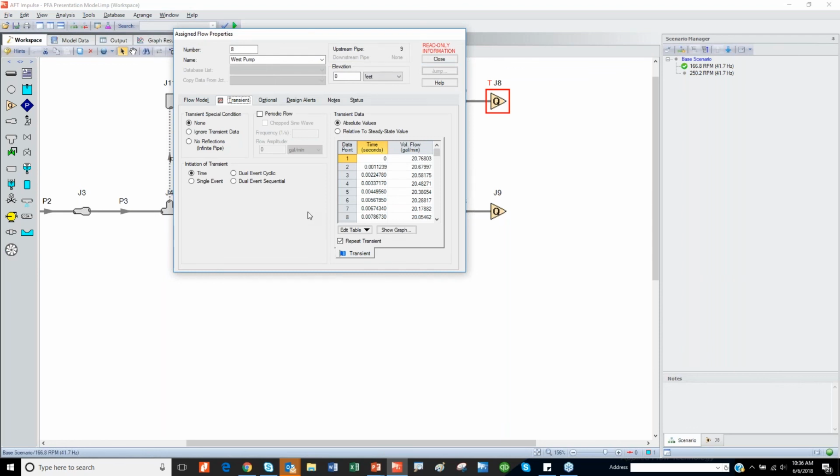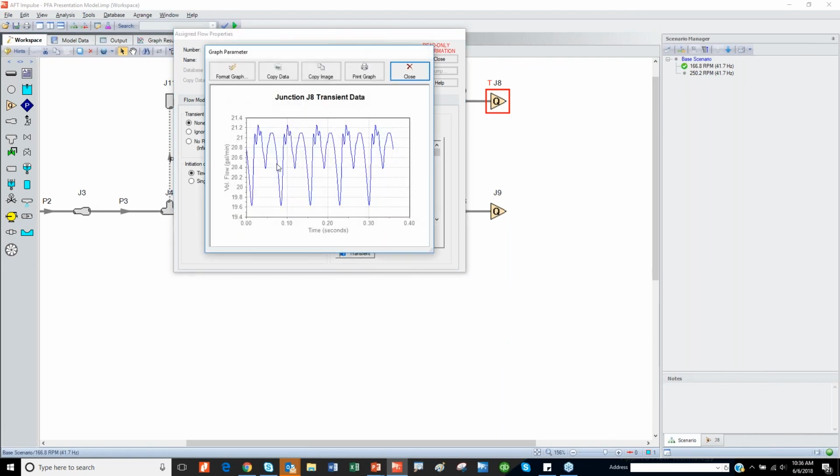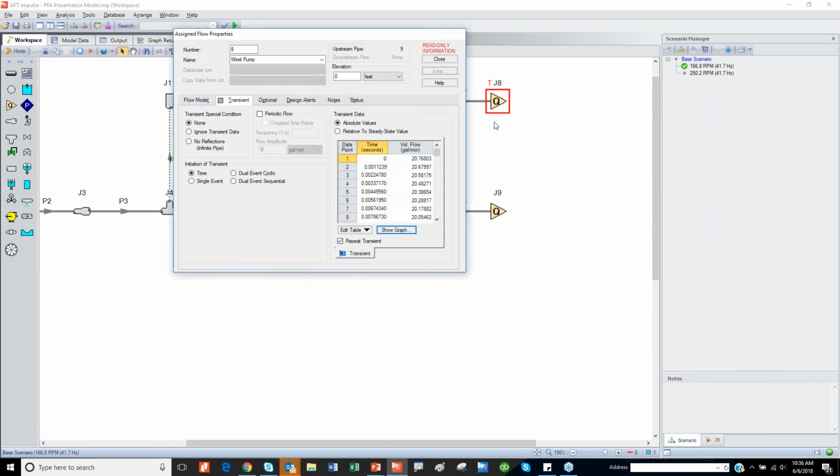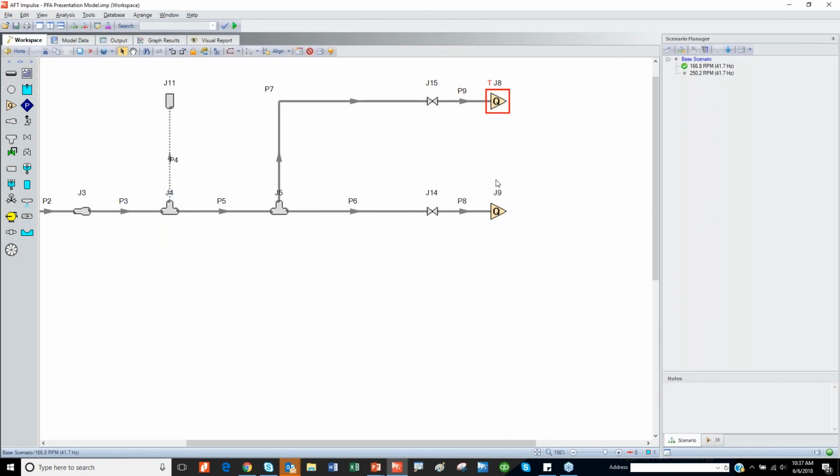So it gives me a message. It will create two pump scenarios with speeds at 166 and 250. And you see that 125 is not showing because I deselected it. So now, if I go to the work page, now I see the scenarios checked, and I say, okay, let me check if I operate my pump at 166 RPM, will it comply with API 674 code? So I go to this scenario.